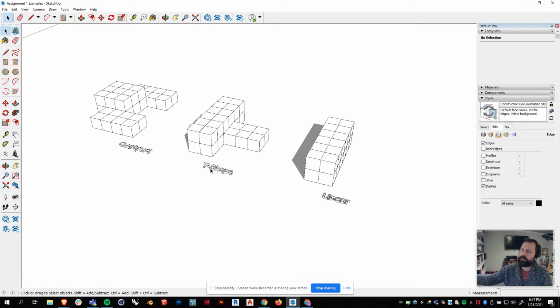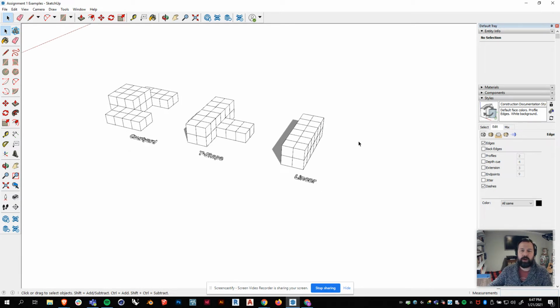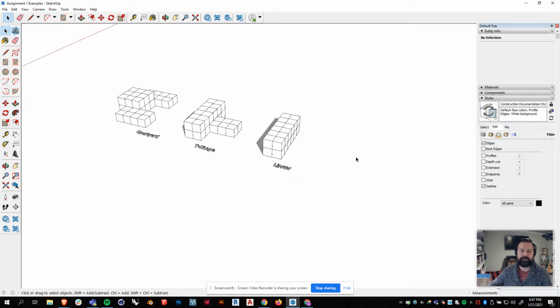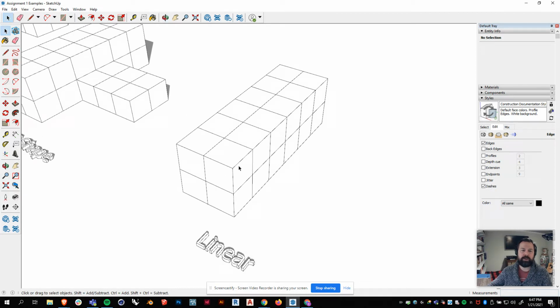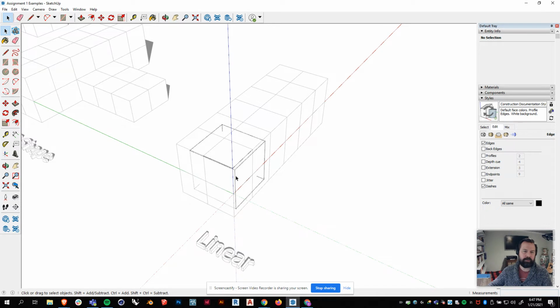Now, in the project write-up, I say that this structure should be at least 15 to 20,000 square feet, somewhere in there. Doesn't have to be exact at all, and it won't be exact, but somewhere in there. So let me show you how to calculate square footage in SketchUp. Now, you could do it this way. I could double click on one of my cubes, select the top plane, and if I look up at my entity info over here, if you just have a plane selected, not any lines, it'll tell you the square footage of that. So it's 576.